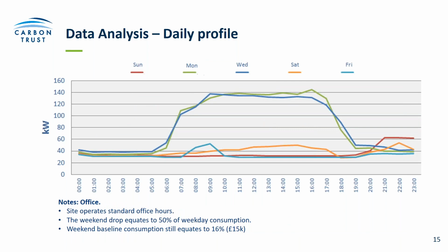And similarly there, with standard office hours, very similar analysis, just highlighting the out of hours consumption. Interesting, that orange line, the Saturday line, where it begins to ramp up at the normal opening hours. So something's been left on the BMS there that seems to be ramping up. It could be the water pipes or the water pumps or something like that coming on.